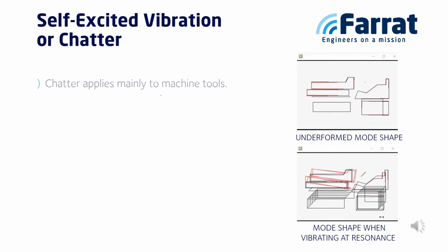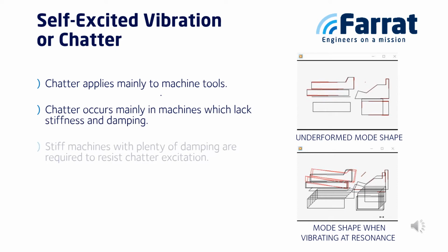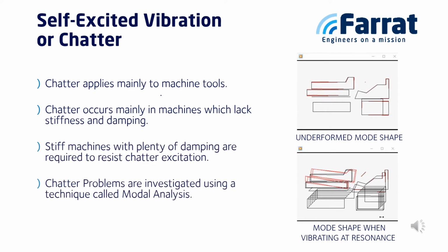In terms of application, chatter mainly applies to machine tools or machines that lack stiffness and damping. In order to resist chatter excitation, you therefore require stiff machines with plenty of damping. To investigate chatter problems, we use a technique called modal analysis.